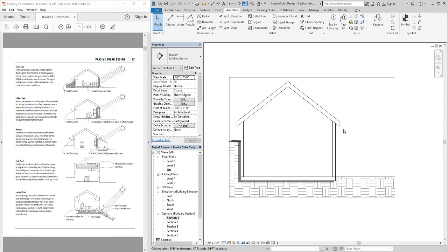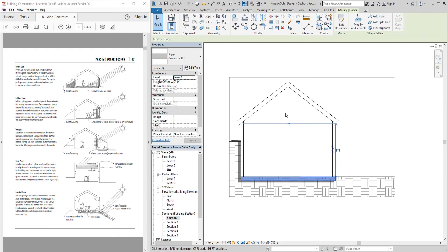We can show the influence an awning would have on our gain and our shadows cast on our structure. But the idea here for direct gain is that our flooring material, and our wall material that is getting this direct sunlight, this radiation heat from the sun, has to be 50 to 60% of the total surface area inside. So I could do a nice stone floor here.